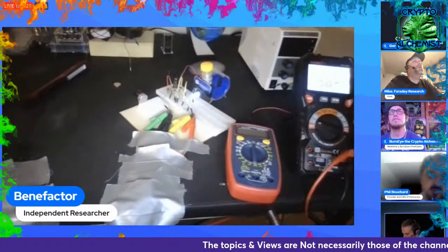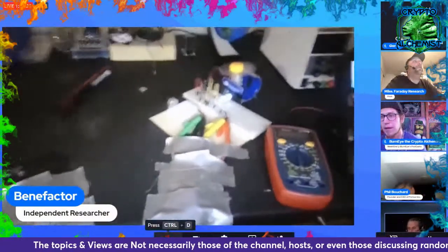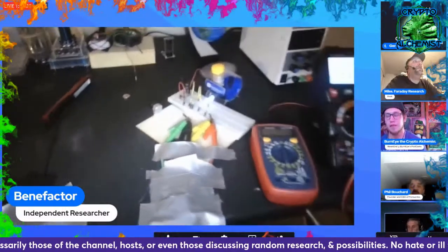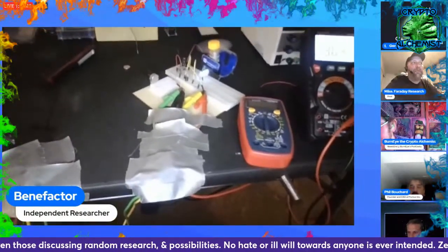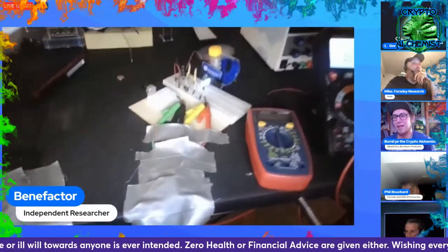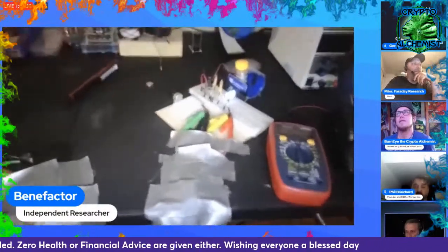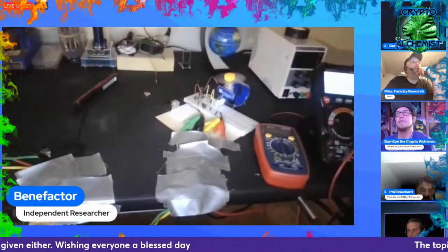I wanted to see how it would affect the DC and the AC at the same time. So, I kind of split the circuit a little bit, but it didn't seem to affect it at all. That's so awesome, man. This is epic. You can power a motor and also power a light. I like the duct tape. But I did notice that without the capacitor, it kind of stops and you have to re-jump it. So the signal's kind of jumpy. Yeah, you have to give it some capacitance. It doesn't have enough capacitance in the coil to drive it. So a capacitor definitely will help.